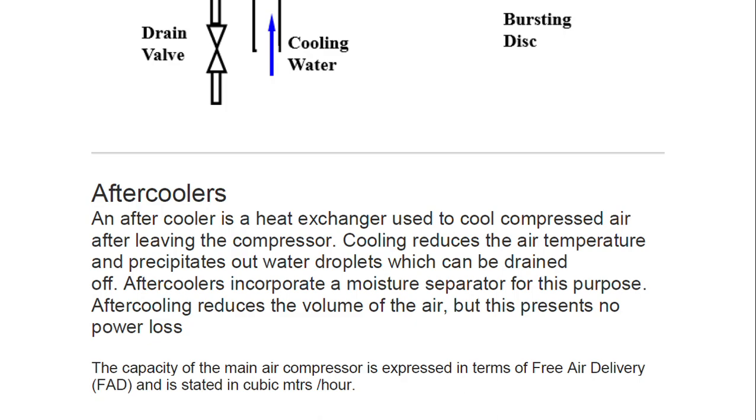Aftercoolers incorporate a moisture separator for this purpose. Aftercooling reduces the volume of air, but this presents no power loss. So there is no power loss. Okay, because in the same confined air bottle, you can store more volume of air when you compress it and bring the temperature down.